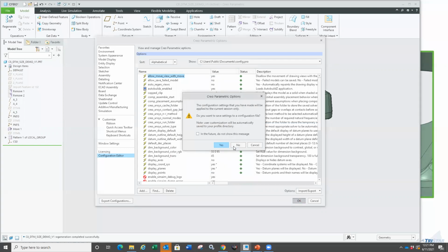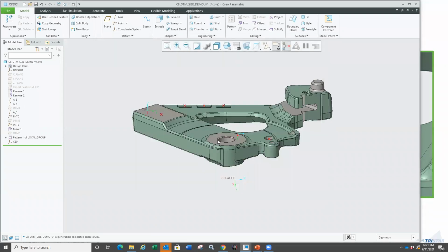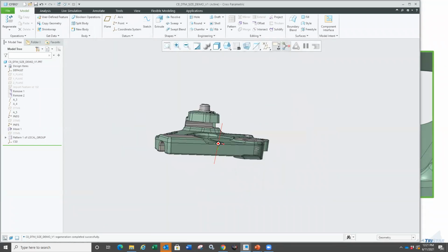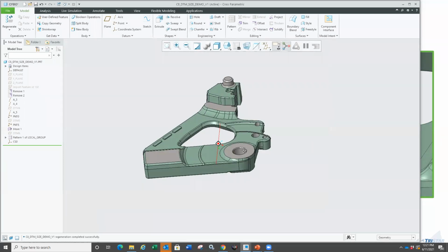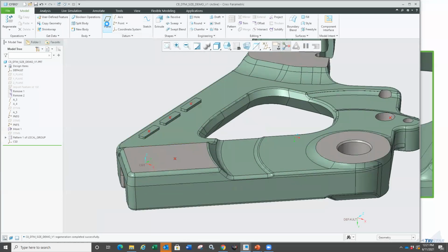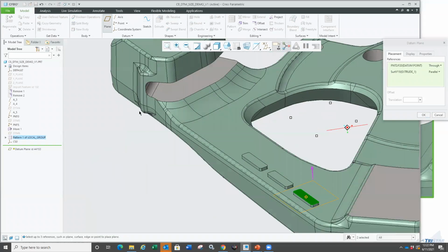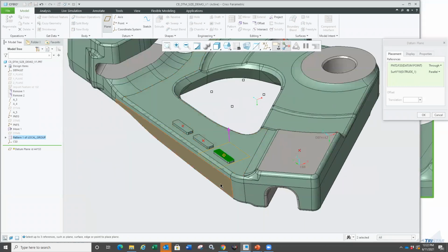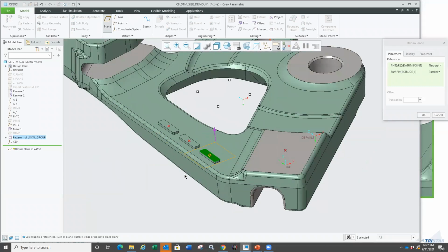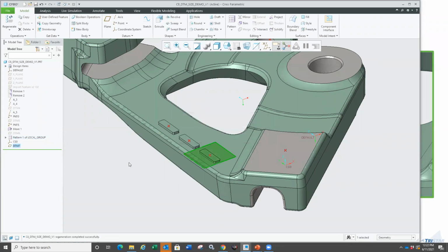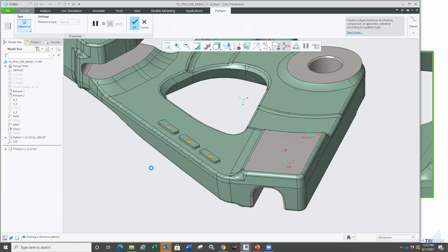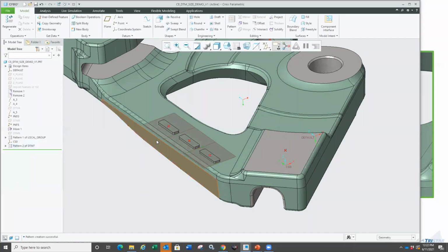And what that does is, now when I create a new plane, let's see here, I'll just create a new datum plane. Maybe I'll just pass it through this point and this surface right up there. You see that the size it's set to is that 20, whatever we had. Of course, I could then pattern that plane as always, just like before. If that point is patterned, things like that, it kind of maintains that size, etc.